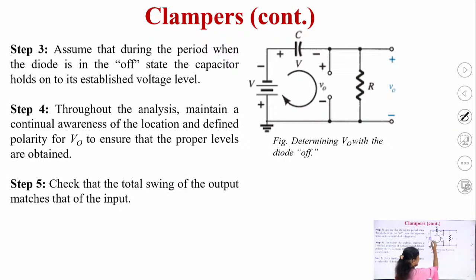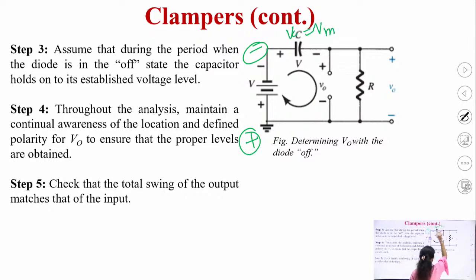Now, during the second half cycle, this terminal will be at negative potential and this will be at positive potential. Also, our capacitor is charged to the value Vm with this polarity marked plus and minus. And the diode position was something like this. I am drawing here just to show you. So, the diode is like this, and here we can see this negative and this negative. These two will get added up and this will make this diode reverse bias.